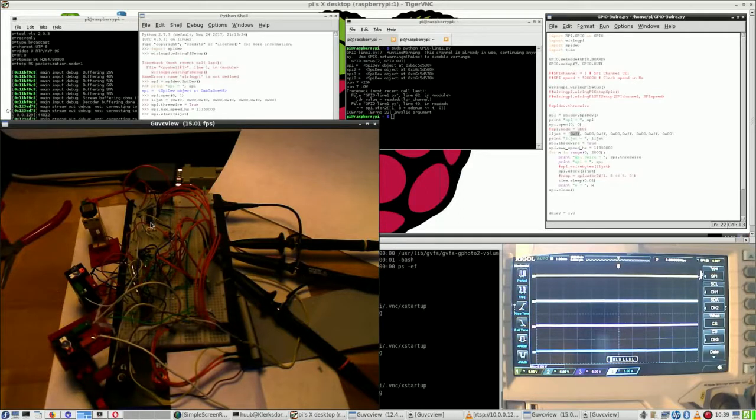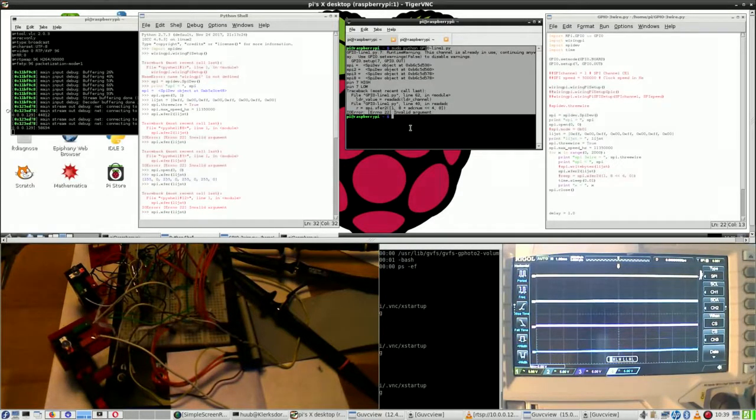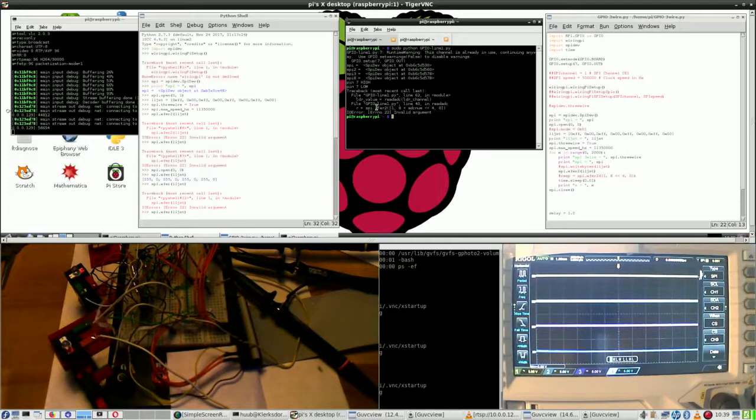Because this, like I said, although it's unplugged now, worked for a long time. This never did. Both SPI, this 3-wire, this is full SPI, but why does this go out while this one worked until now? Because you can see that this is failing now on transfer, the transfer of bytes.